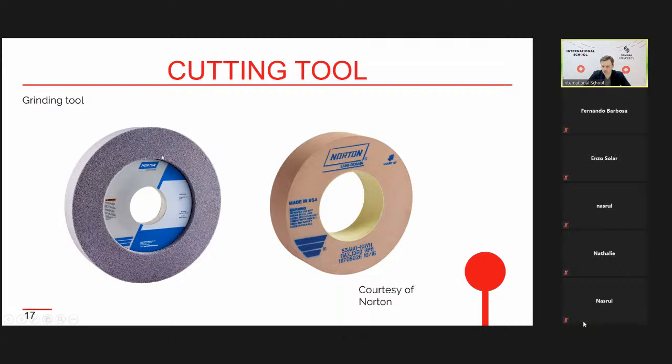But also you can see here that this grinding wheel is made of some material similar to sand. So you can see that it's not a solid part of some material. It's an abrasive cutting material which is, let's say, clamped by a special bond. Bond holds separate abrasive particles and forms the final shape of the grinding wheel.